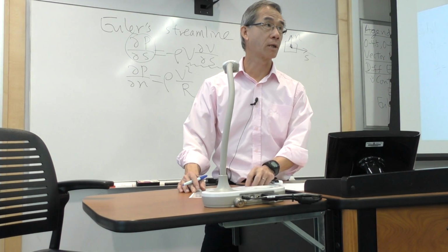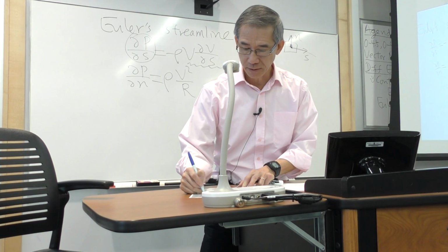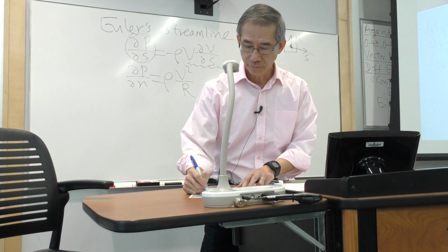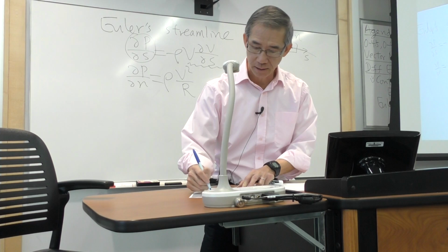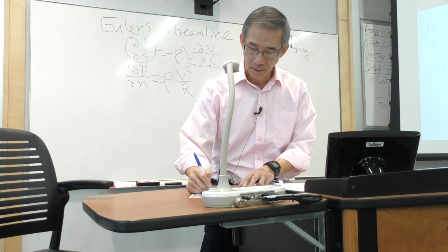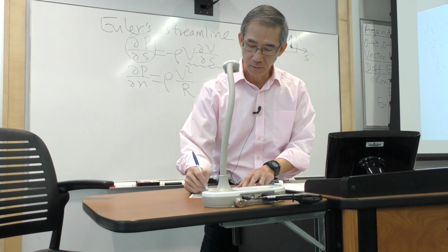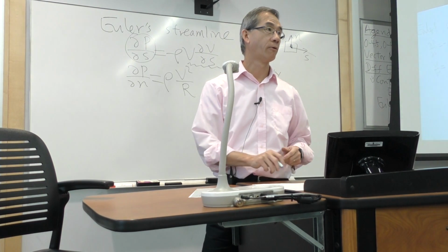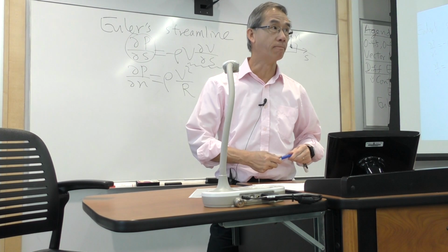Now, if I were to come up with a momentum equation, what I have to do is have the same approach, dx, dy. The theta now becomes my momentum flux, which is rho u A, that's my mass flow, times the velocity u again. And that's per unit area, is now my new theta for the Euler's equation, which is the equation of momentum.